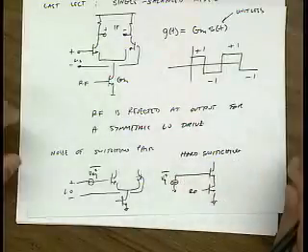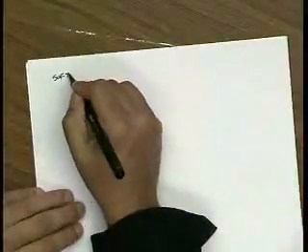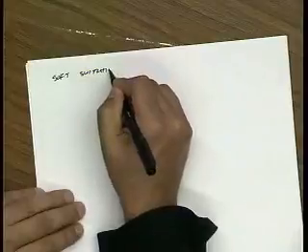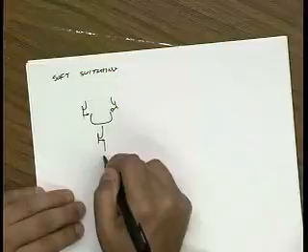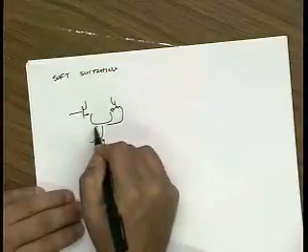On the other hand, if I do soft switching, then both devices are actually on, and it looks like a differential pair, which has gain to the output.